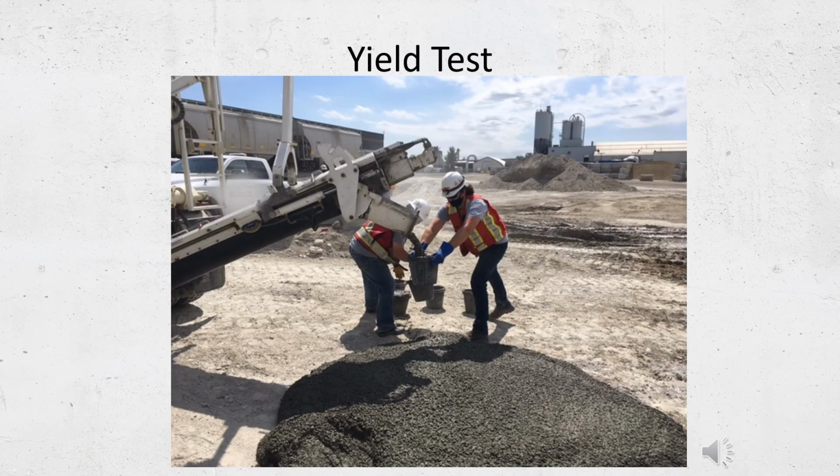Now that we've got all of our materials dispensing rates calculated and set, let's start making concrete. Start up the unit and discharge concrete until a continuous uniform concrete mix within the selected target and slump range is established. Then pass a sampling device through the discharge stream to collect a minimum 25-liter representative grab sample. Stop the conveyor and auger. If a chute is used, it should be completely emptied. The auger must remain full.